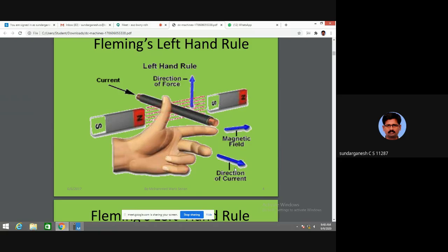If the direction of the current is reversed, for example moving from inward to outwards, or from outwards to inward, the motor direction will be anti-clockwise. Okay. So depending upon the direction of the current in the rotor, the motor rotates in a clockwise or anti-clockwise direction. The magnetic field lines are constant. You are giving a DC current, so the stator magnetic field direction is always constant. The direction of the current induced in the rotor depends upon the supply you are giving.